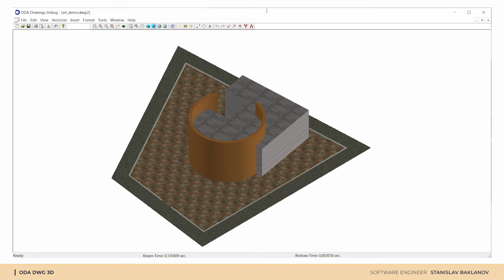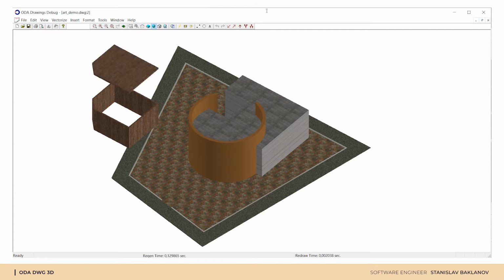Next, for two colored regions, we perform Boolean intersection. Copy and scale region and make subtraction to get a region with a hole. We use extrusion and get a solid representing walls. Then we add a roof using Boolean union.